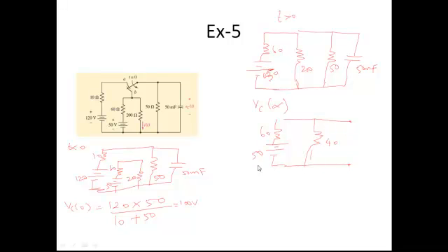So again I apply only the voltage division rule. So you are finding Vc of infinity now. Total voltage into the same branch resistance, 40 ohms, divided by the sum of the resistances, 60 plus 40 ohms, 100 ohms, which gives you 20 volts. Okay, now you got the answer for Vc of infinity, and you got the answer for Vc of 0.